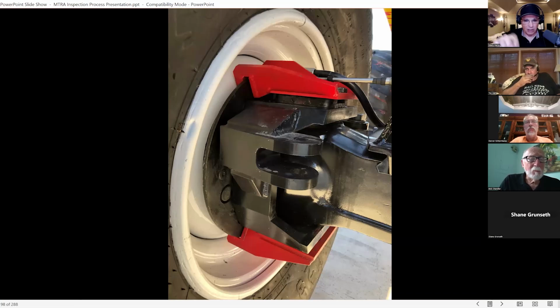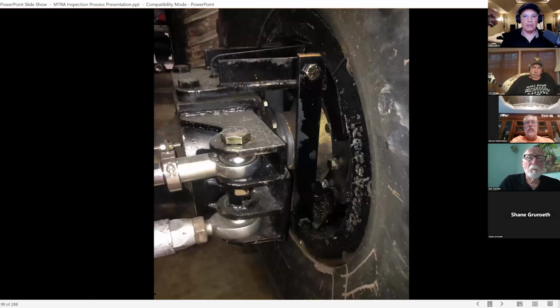See, the red plates here are capturing that disc, but the problem is that when they're independent like that, all the load is taken by one or the other at any given point, because sometimes wheels break going down rather than up. So it just depends on the situation. So it's very important that those things be tied together, as you see here. In other words, they're still individual plate capture points, but they have a strap tying them together so that they're moving in unison.